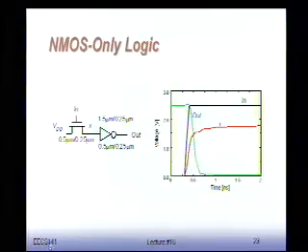And this simulation shows you exactly that. As you can see, my input goes up. My node X lumbers upwards and gets to VDD minus VTH. The output after the inverter follows very nicely. Once I get to the 50% point here, this output will start dropping quite nicely, so that's cool. But you see at the end, the VGS of my PMOS device is, in this case, actually more than 1 volt. Not a very happy situation. That thing is going to leak like a sieve.